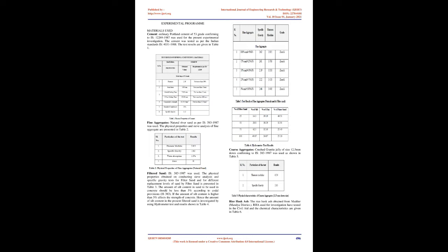than 80 to 85%. Surface soils from tank beds, agricultural fields, and village common lands have been excavated and washed to produce a kind of artificial sand in order to meet the enormous demand, known as filtered sand. Only source materials with suitable strength, durability, and shape characteristics should be considered. Production generally involves screening and possible washing. Separating into discrete fractions, recombining, and blending may be necessary. Therefore, the utilization of rice husk ash, RHA, and filtered sand, FS, in concrete for the replacement of cement and sand is environmentally and economically advantageous.